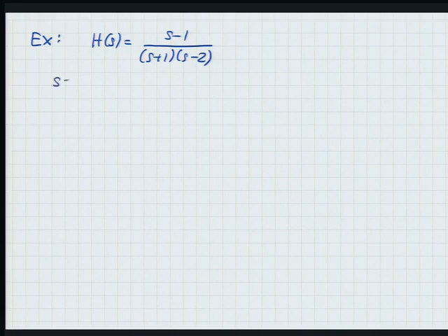Poles at -1 and +2. Stable? No. Who's the culprit? This one. Right half plane is not allowed. Again, what went into this is, if you look at possible h of t's that give you this h of s, and ask which ones are the causal ones.